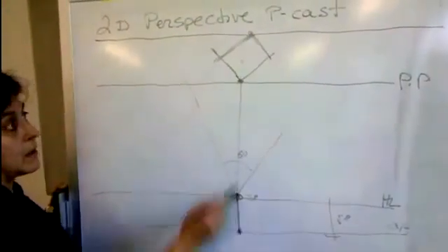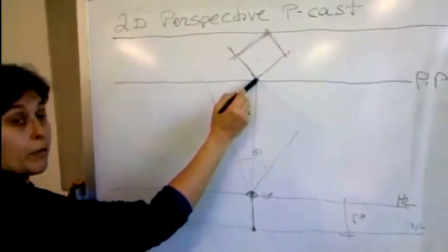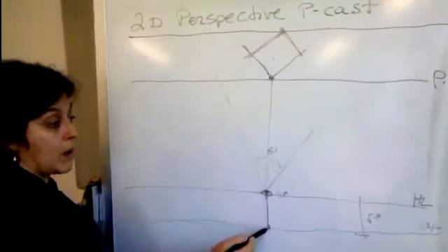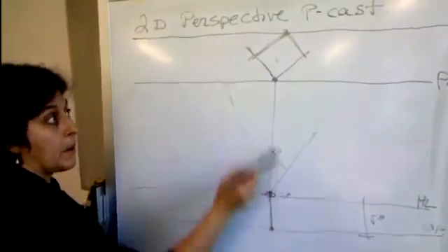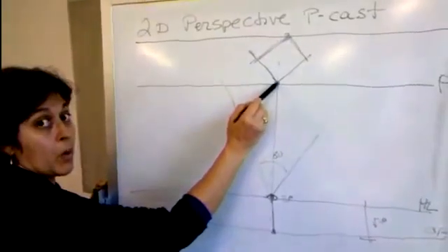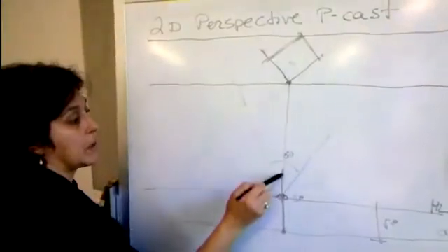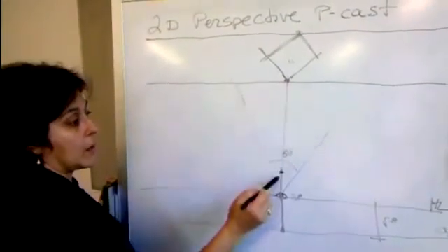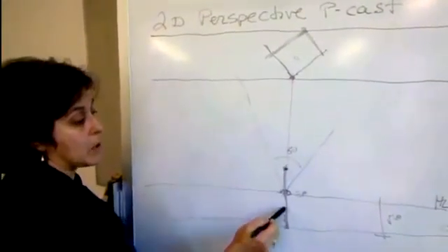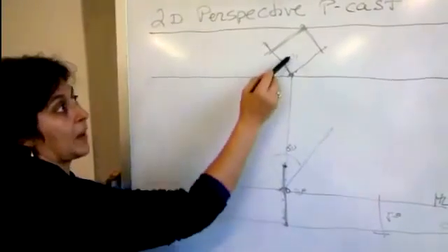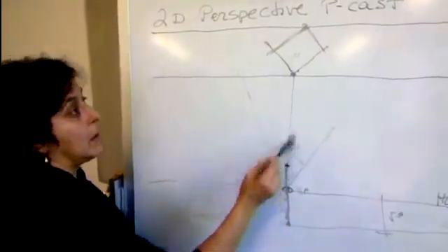That point, directly below the point on the floor plan that hits the ground plane, is the bottom of that corner of the building. You measure up to scale at the same scale as the building, however high that corner is. If it's 8 feet, you're measuring 8 feet at the same scale as that building.